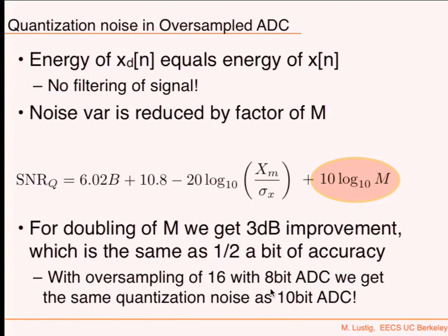But of course, if you had a 1-bit quantizer, right, and you sampled it at 1,000,000 times faster than the Nyquist rate, it turns out you will be able to reconstruct your signal quite well. With a 1-bit quantizer, you will be able to reconstruct your signal quite well. You can think of it from the digital to analog side. There's pulse width modulation, like the Arduino does, where if you want to produce half the maximum output, the Arduino would basically put a voltage on for half a cycle and then off.